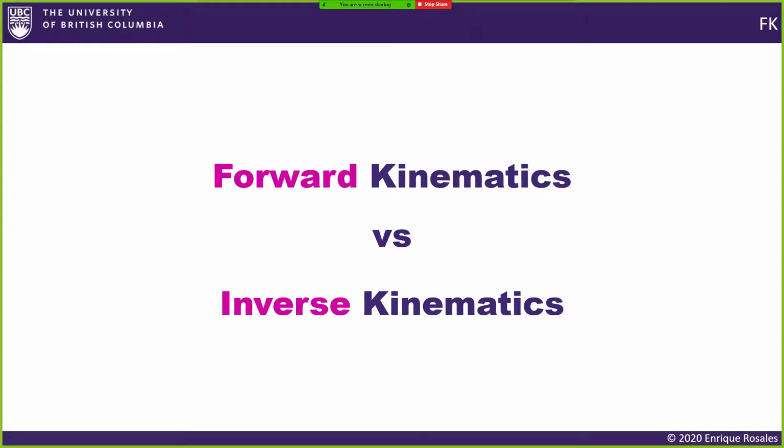Nam is asking, does IK involve Jacobian transpose? Yes, it could. The thing is, inverse kinematics is very complicated, and in robotics it is very sophisticated, because for robots you need to actually take into account the mass of the robot. I will show you who the Jacobian is. I will show you the simplest version of inverse kinematic, which is useful for computer graphics.